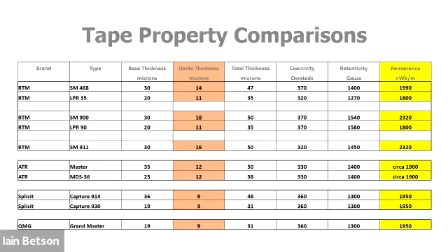How much flux? We've covered all that in our phi equals BA cosine theta equation, and it's measured in nanowebers, our magnetic flux. 1990 and 1800 for our LPR35. So in other words, our LPR35 will not give us as much level, will not give us as much recorded signal on replay as our RTM468, in spite of the fact that it's the same tape formulation, the same oxide dispersion in the tape formulation.